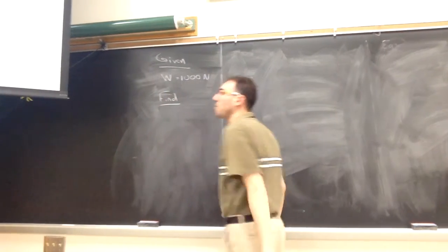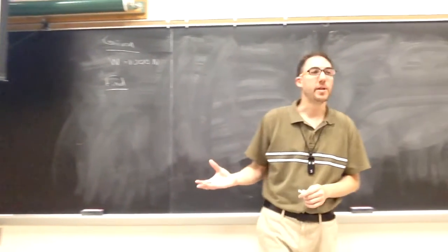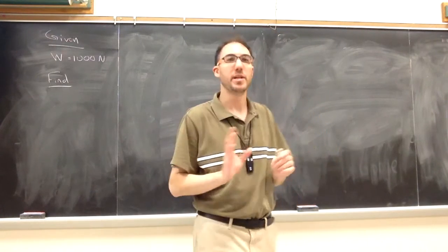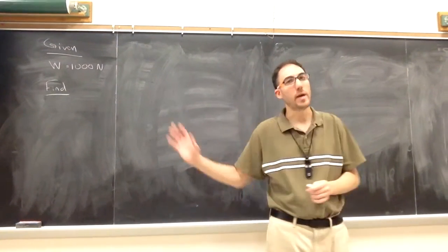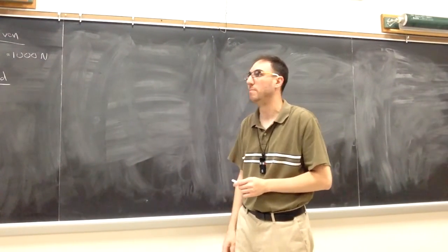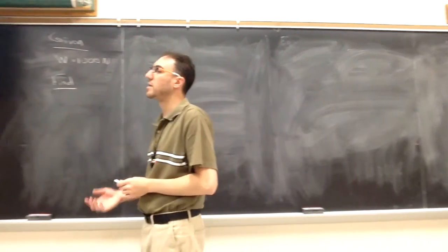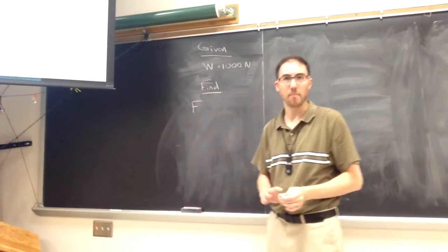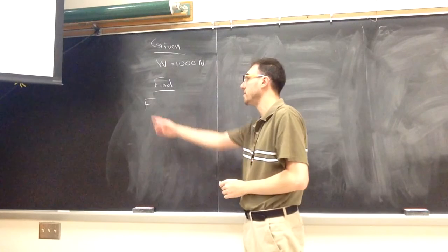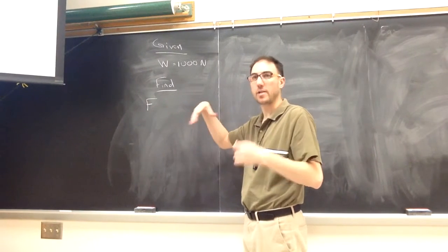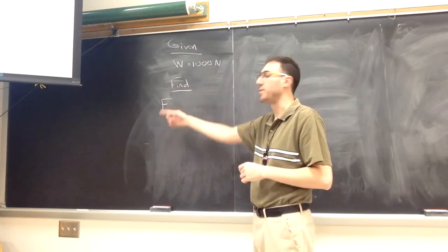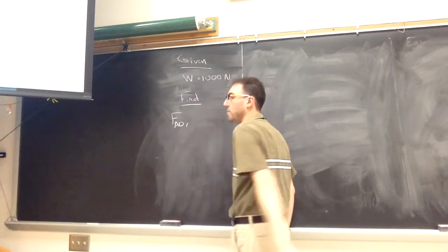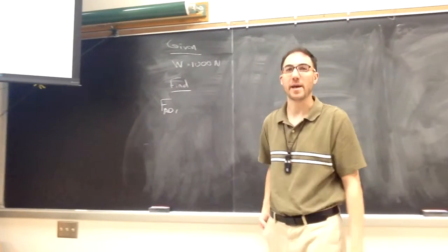And we want to know, what are we asked to find? Well, we need to know the forces in all three of these things. But the naming convention I'm going to use, I'm going to continue throughout the whole problem. There's two rods, so each of them can carry a force that could be in tension or compression. So I'm going to name things that are forces that can hold tension or compression. I usually will use F as that name, and then the points at which it passes through. So there'll be a force in the rod that goes from A to D.